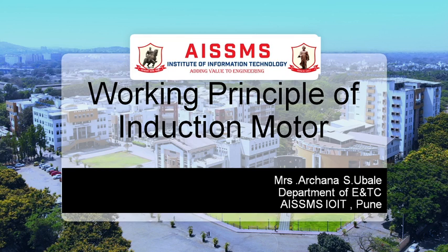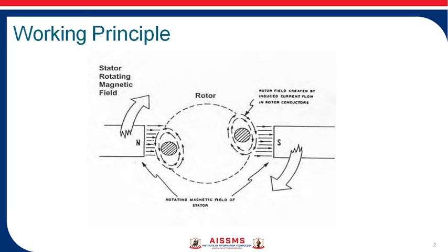I am going to explain the working principle of the induction motor. Actually, the induction motor works on the principle of electromagnetic induction. In a three-phase induction motor, when a three-phase supply is given to the three-phase stator winding, it generates a rotating magnetic field of constant magnitude, and the speed of that rotating magnetic field is called the synchronous speed.